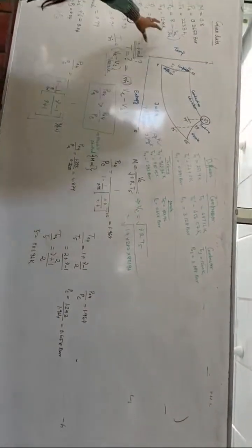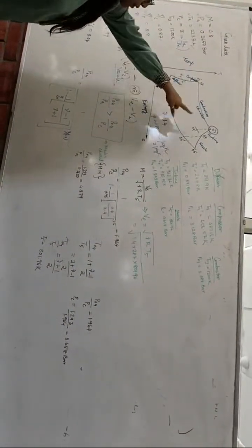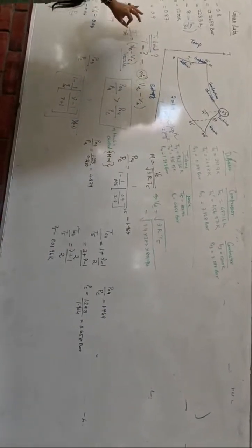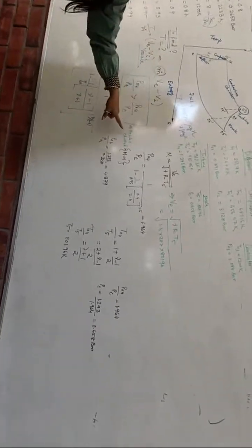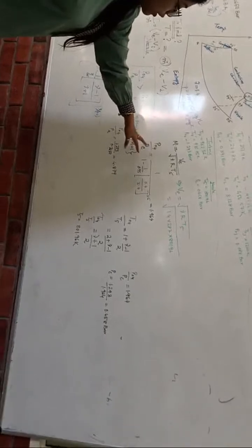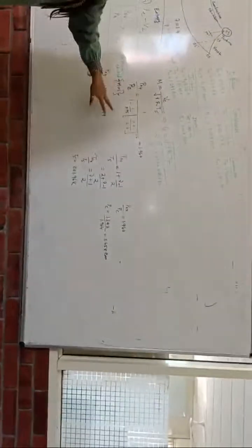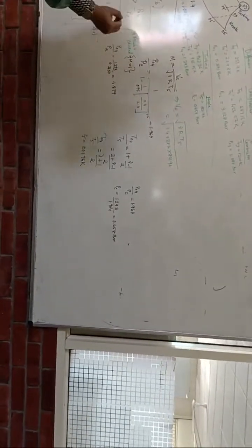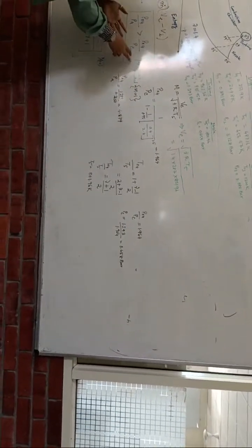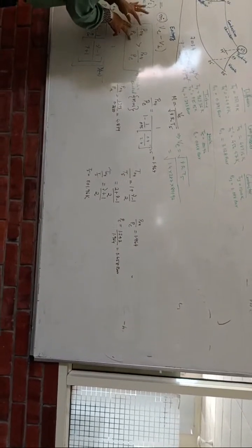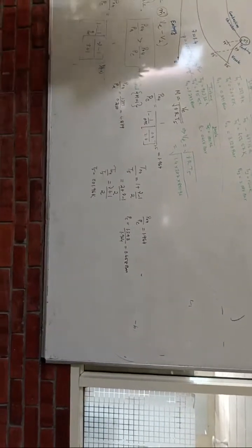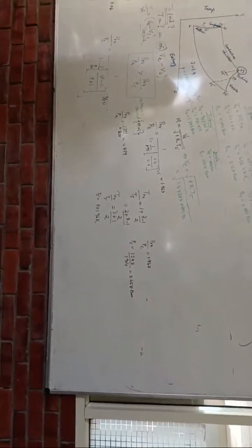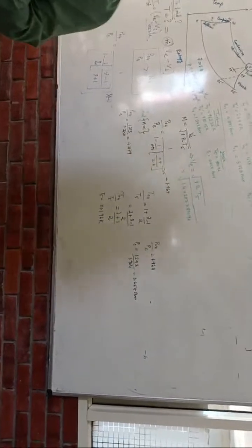Clear? So step by step you have to move on. Same formulas, application of the same isentropic relation, and at the end, in the nozzle part, you have to check whether the nozzle is choking. If choking, you have to consider the Mach number is 1. Considering Mach number 1, we find these ratios and find the temperature. If it is not, then we follow with this P04 by PA value, and the whole procedure is followed to find the answer for the exhaust velocity. Okay, I hope you have understood and you can check this video.